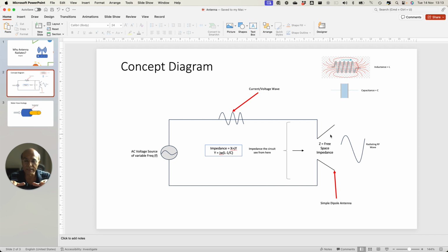But if you are going to a lower frequency band, let's say the 700 or 600 megahertz band, even though the propagation of the RF wave will be better in the lower frequency band, because of this issue of antenna length, packing this length of the antenna in the shorter form factor of the mobile phone, the propagation will actually be similar to that of the 900 megahertz band. So a low frequency band does not give you better coverage. Why is it not going to give you better coverage? Because of this particular problem which nobody really focuses on.